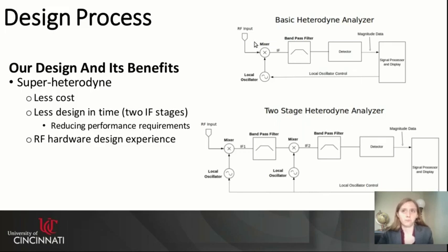In this diagram, we have a basic heterodyne design. We have an input frequency, a local oscillator frequency, and a mixer. This configuration allows us to either up-convert or down-convert the input frequency to a desired intermediate frequency. The IF frequency typically depends on our later component specifications.